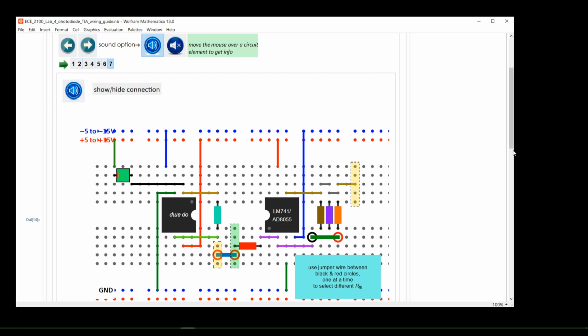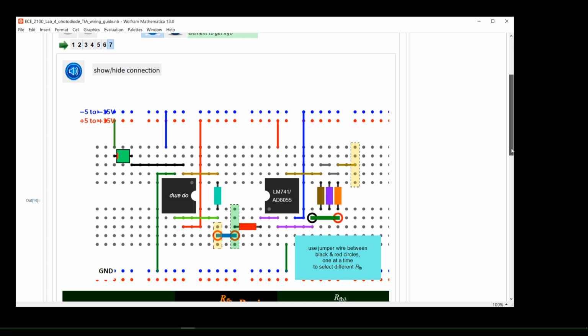To use it practically, the photodiode transimpedance circuit output should be connected to the input of the voltage amplifier circuit. In other words, 2 stages of amplification are needed. The first stage with the transimpedance amplifier is to convert the photocurrent to a voltage signal. The signal amplitude is usually still relatively low at this stage. The second stage amplifies this voltage signal by a factor from 10 to 100, depending on choice. The combined circuit is an optical receiver, and is now ready for testing.